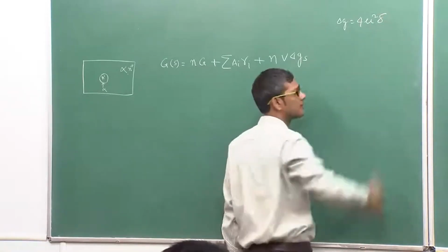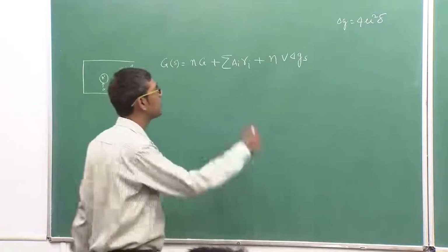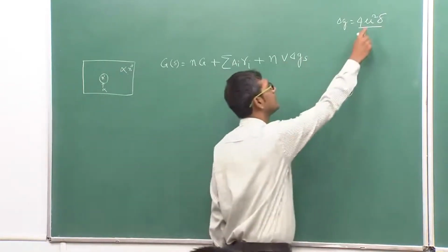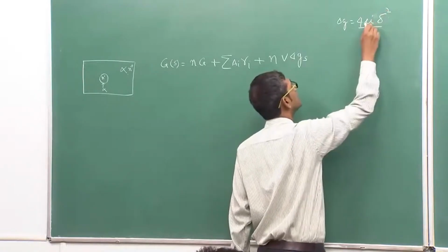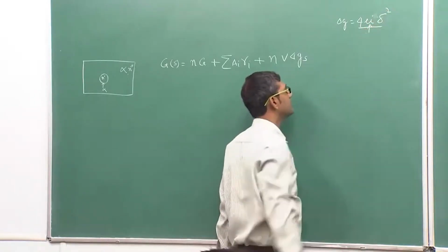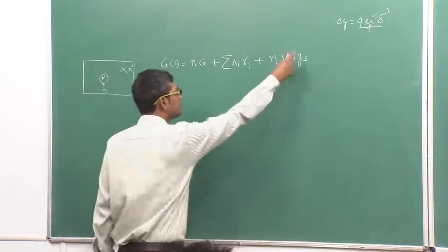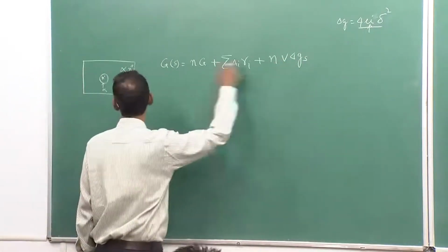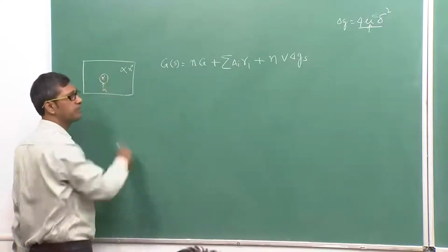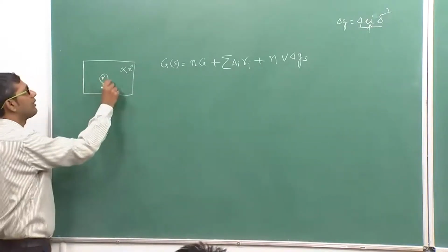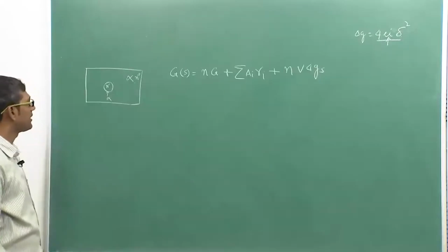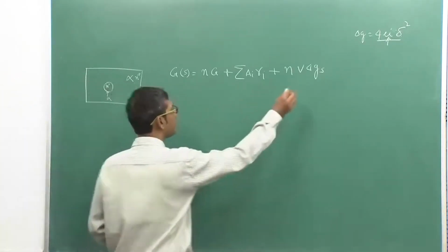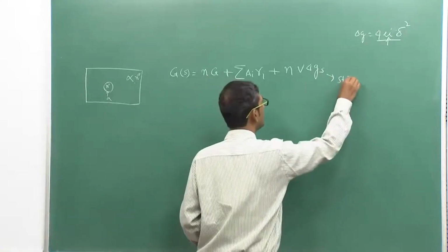Anyway, this is nothing but a strain energy, because this is your shear modulus and this is the misfit. This can be calculated by many means. The fact is that there is a strain at the boundary between these because of the misfits, so you will have an extra energy term. So, let me write down these same things for both, and this is per volume, remember, this is strain energy per volume.